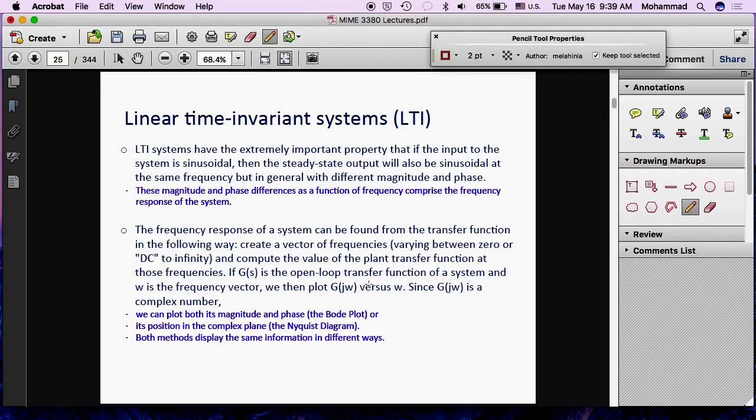Okay. Another way of characterizing the systems that we investigated so far is to call them linear time invariant systems. Linear, we discussed. A linear system is a system that when you double its input, the output would double. That's an indication of a linear system. And the way to have a linear differential equation is to have all the elements as linear elements. So no power 2 behavior, no square root behavior, power 3 behavior, things like that would not enter our differential equation. Now, the fact that a system is time invariant on the surface may be misleading.